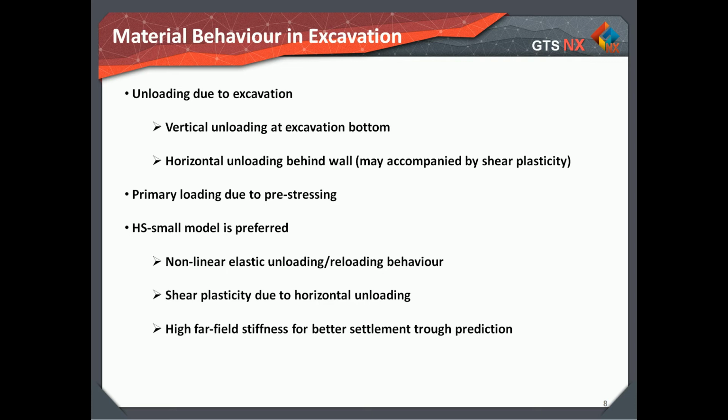Thus, a constitutive model which incorporates nonlinear elasticity, particularly at small strain, should be used in this circumstance. When choosing a constitutive model, the following aspects need to be considered: soil nonlinearity, actual resulting strains in the ground due to excavation, and techniques for determination of ground stiffness.